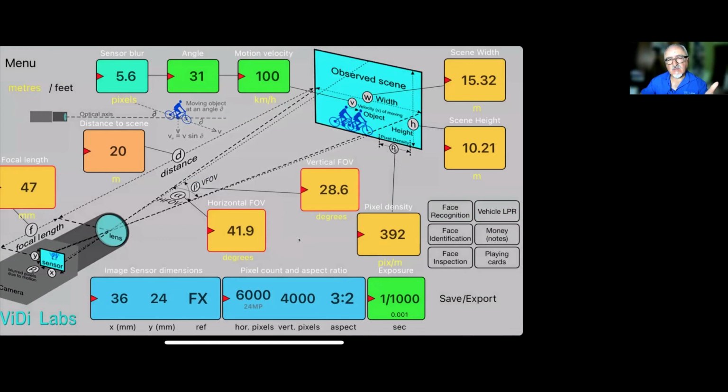So you can achieve, even with a CCTV camera, number plate recognition or reading, providing you understand how to position the camera, providing you understand how much light you've got, and providing you have the best possible camera for that purpose, which in my opinion, if it is a CCTV camera, should be a camera with a large sensor and large pixels, which basically will capture sufficient light even at low light intensities. Or if that fails, you probably will add infrared light or strobe light to add to the illumination in low light. So that's basically all that I can explain for the